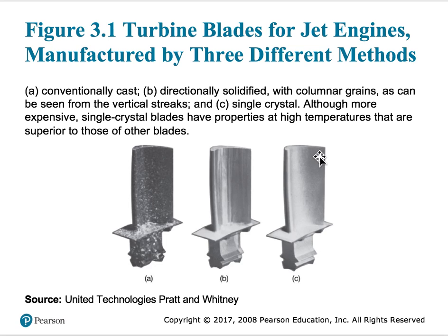And the reason is that many times creep is a hidden killer, and this component can fail in service, which means that once it breaks, it is rotating at a very high RPM and it can go and bang up against the wall of the engine and make a hole, which means that the engine can fail right in service. You do not want that.